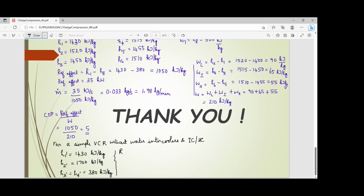Okay, so my refrigeration effect is going to be H1 dash minus H3 dash or H4 dash, however you want to call it, both are one and the same. 1430 minus 380. I think that is once again 1050. There is no change in the refrigeration effect.